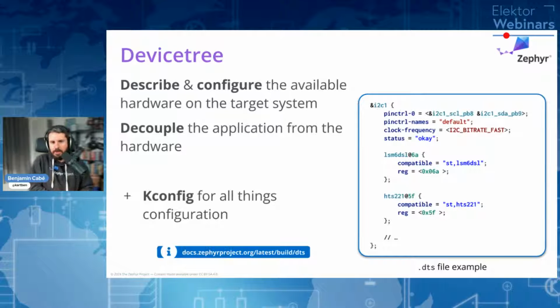That means that you might have trouble porting your application from one device to the other, because all this initialization code you would need to write again. So device tree is actually quite interesting and quite important. We'll see it a bit as part of the demos, and it goes hand in hand with something called kconfig, which is really powerful in terms of providing you a way to easily, and back to the question of whether Zephyr is suited for battery-powered devices and small devices, the ability to really configure what ends up being your final application.